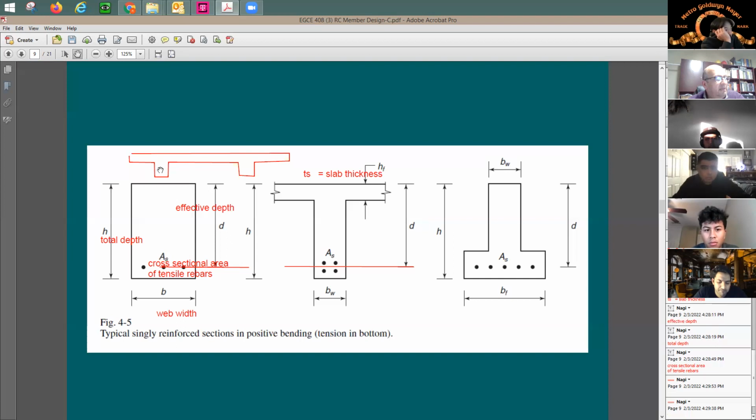So someone's gonna say you have a beam here and this is gonna be like a free end. So maybe take this free end, consider it to be part of your T section. And then here, take it half the way to the other beam. So you say, let me take it from this beam to the mid span of the slab, half the way, and this is gonna be your section. You say, yeah, let's say that this is okay for now, and let's see what the code says about this effective flange width. So now you have an idea about the meaning of rectangular section and T section, and the symbols that we're going to be using for our variables.